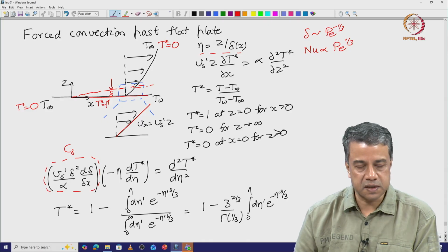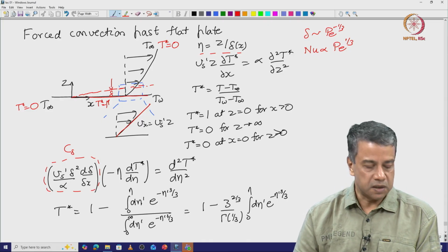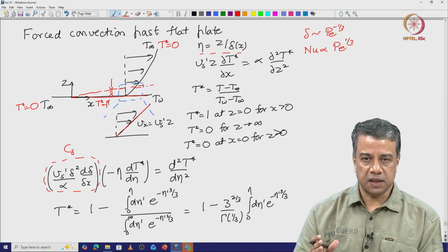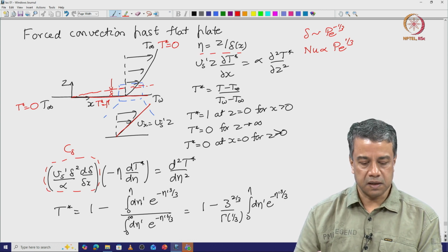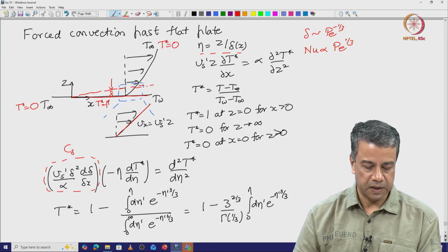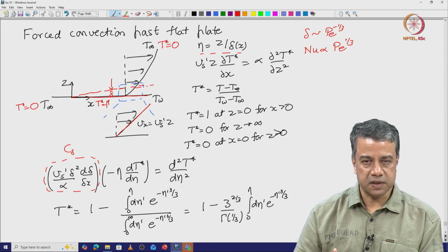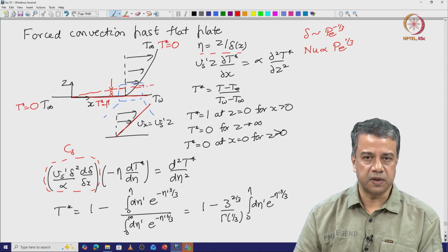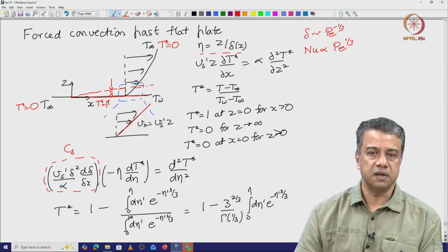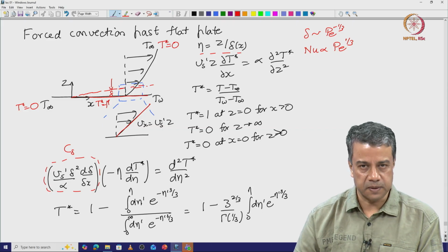The average velocity is mostly due to the velocity near the center of the channel. Close to the wall, the velocity has to be small, because at the wall itself the velocity decreases to 0. Therefore, close to the wall, the velocity has to be a linear function of distance from the wall.